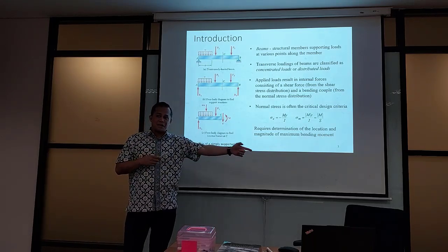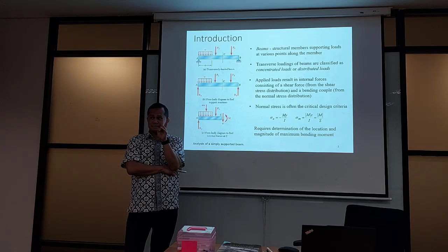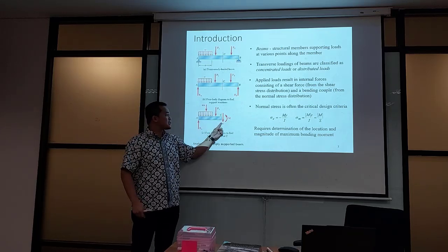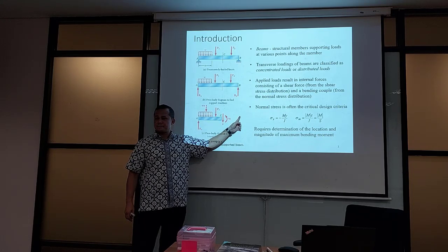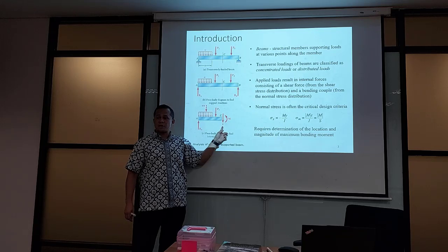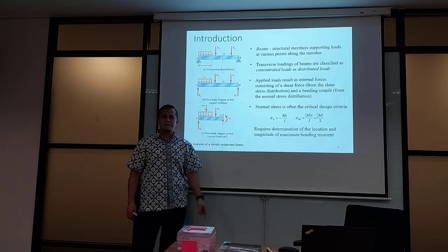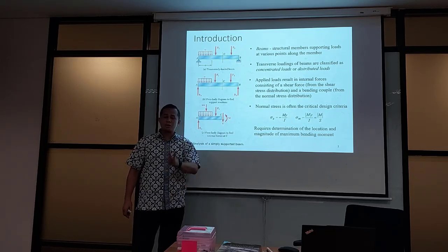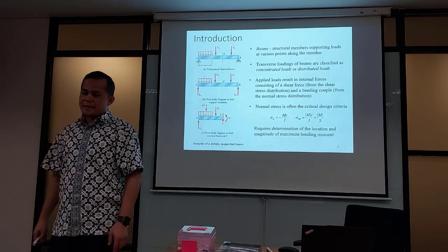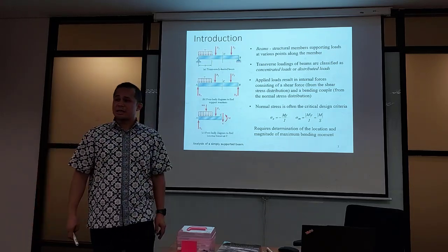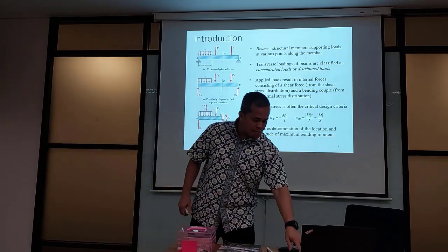In the previous chapter there was tensile and bending, and both of these generated normal stress. In this case, you have shear force and bending. Bending will generate normal stress or shear stress? Normal stress. The V will generate normal stress or shear stress? Shear stress. So this will generate shear stress, this will generate normal stress. Two different loads, two different kinds of stress. Okay? Now we will try to define the distribution of shear force and the distribution of bending throughout the beam.